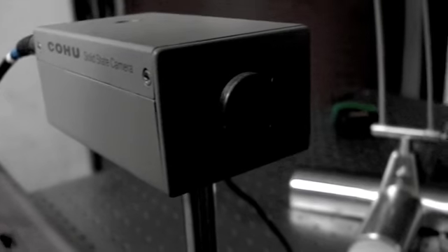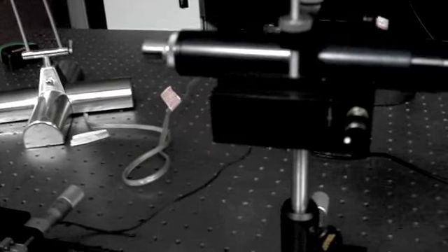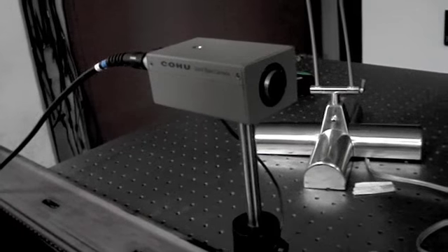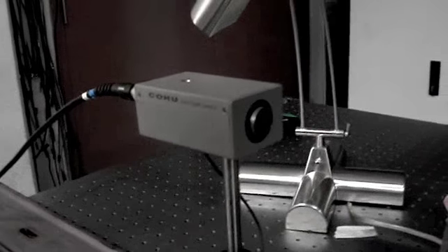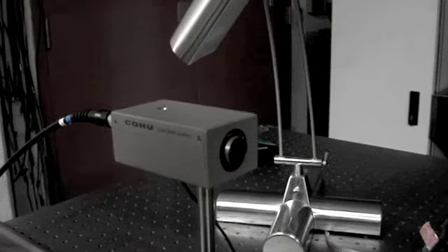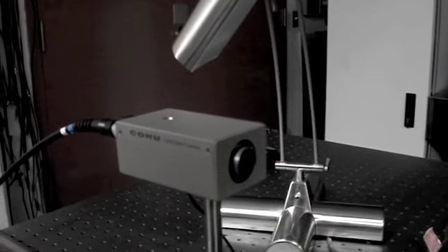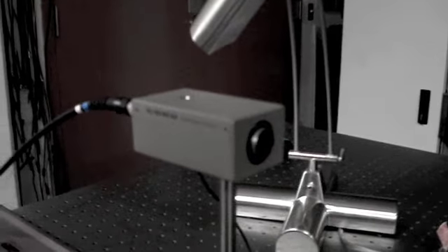Using the same procedure that we used previously, we measured the size of the CCD using the microscope, and we knew that it was 480 by 640 pixels, so we found our pixel size to be the same, which was 10 by 10 microns. From then, we also measured the field of view using the same procedure as before, and we found that we had an 81 degree width and a 62.76 degree height.